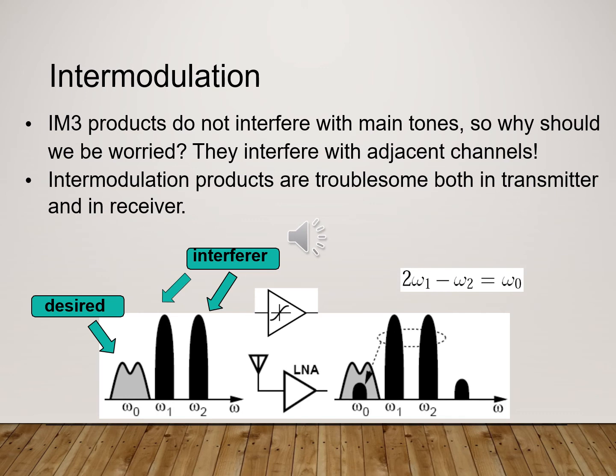Now, as you recall, intermodulation is a situation where there is a combination of undesired frequency components within an active system or from an external source. A combination of two or more signals will create another signal which may fall into another frequency band of the system and cause interference to this system.